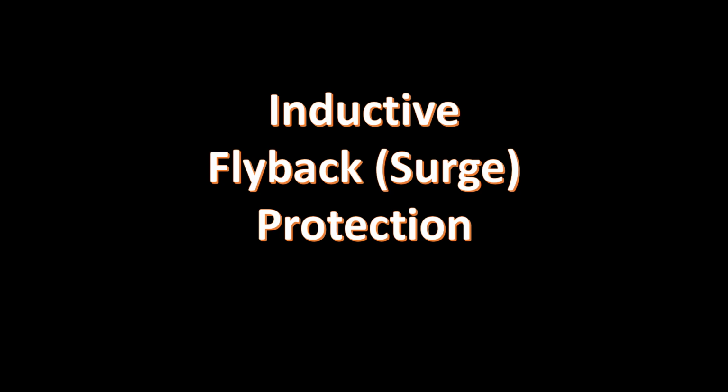Today, I want to talk to you about something that I call inductive flyback. It's an old term. Flyback is an older term. Some of you might have heard it as inductive surge or inductive kickback. But when we're wiring inductive loads to a programmable logic controller, or really to any microcontroller that uses solid state switches to turn outputs on and off, we have to protect those switches. So I want to talk to you about inductive flyback protection.